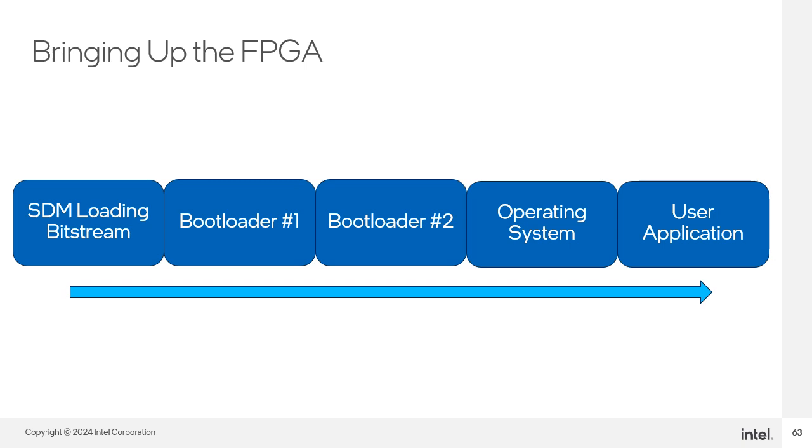You can create the SSBL from U-Boot or the ARM trusted firmware, both of which can be found on GitHub. The operating system is the third boot stage for the HPS. The second stage bootloader loads the operating system stage into SDRAM. The OS can be Linux, Zephyr, or bare metal. The OS executes from SDRAM. The last boot stage is the application that runs on the OS.